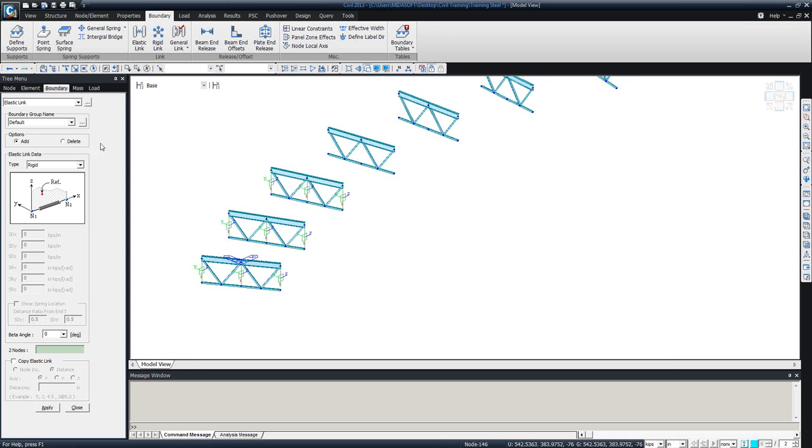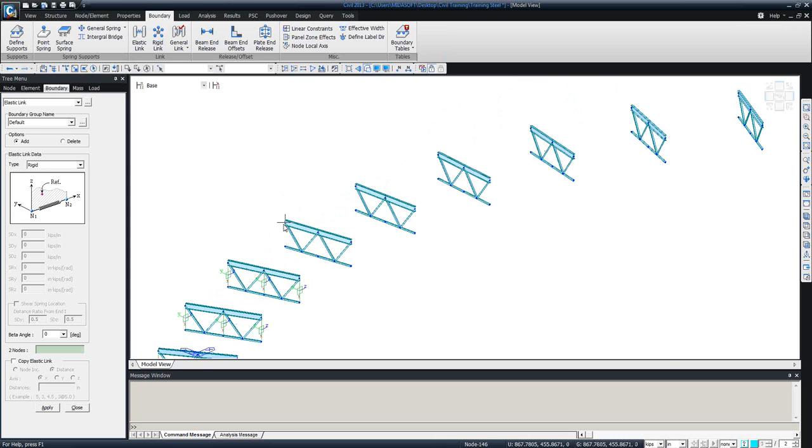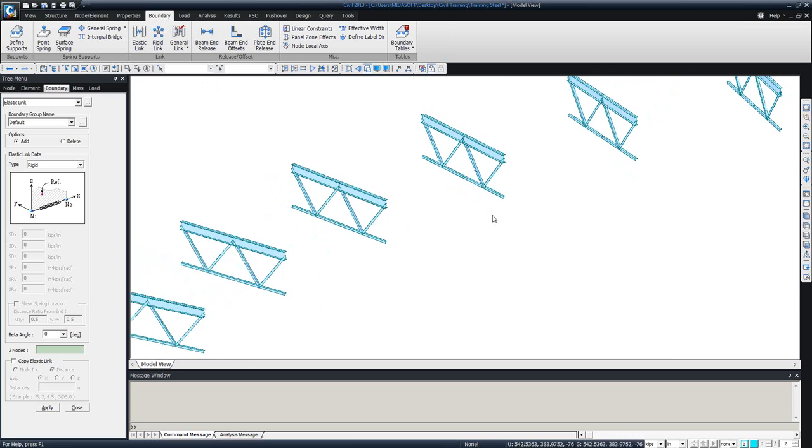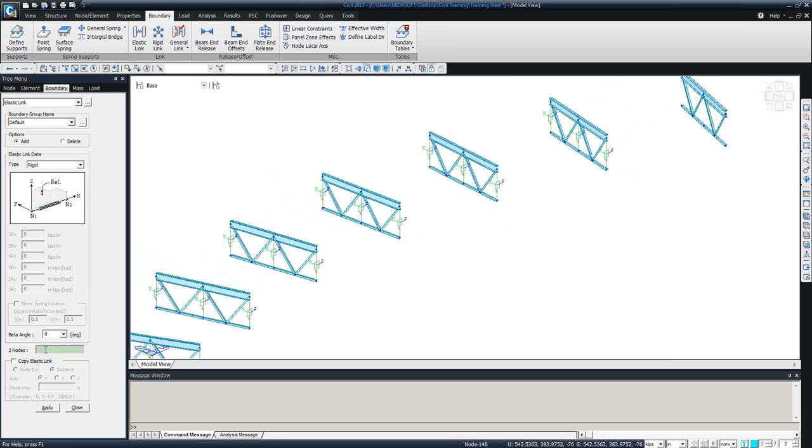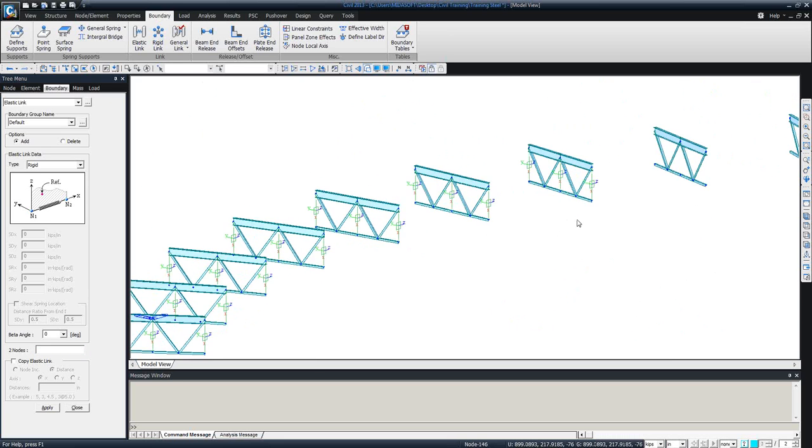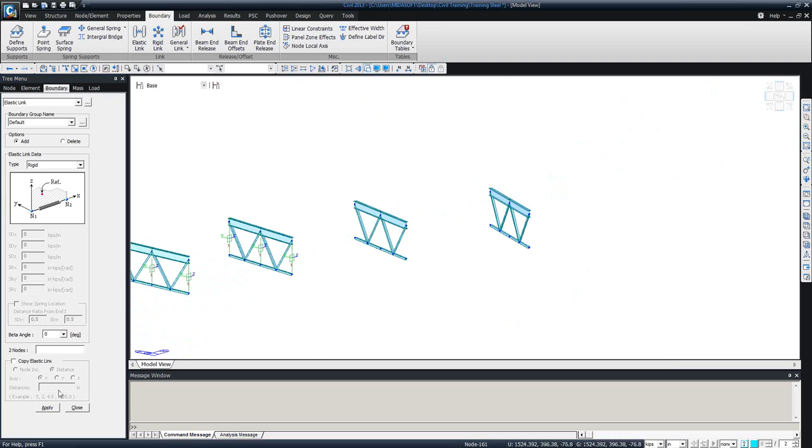And if you're doing the construction stages, which we are not modeling today, ensure that you select the correct boundary condition, because construction stages are all about the groups. So at that point, we're going to have the structural groups, boundary groups, and load groups, and then we're going to activate and deactivate them at different stages of construction. All right, so I've got 2 more.